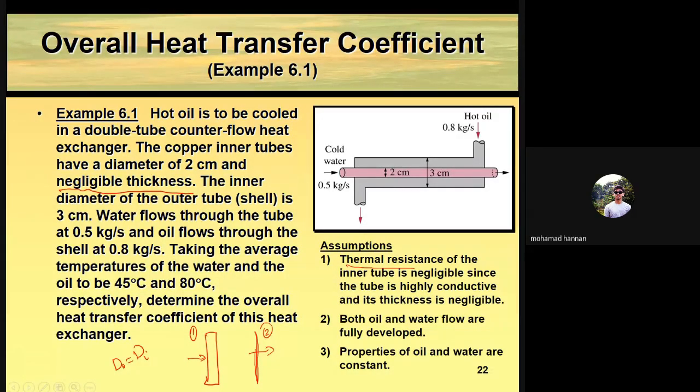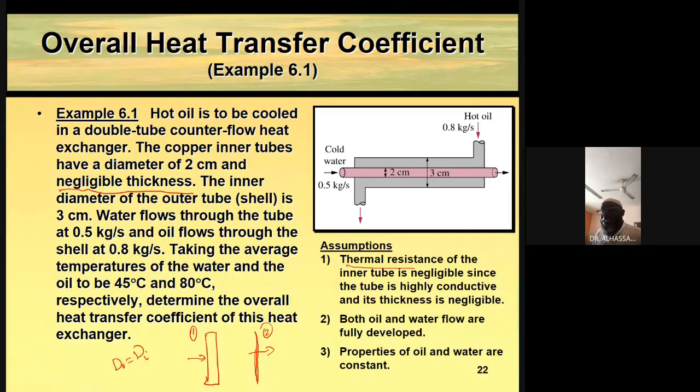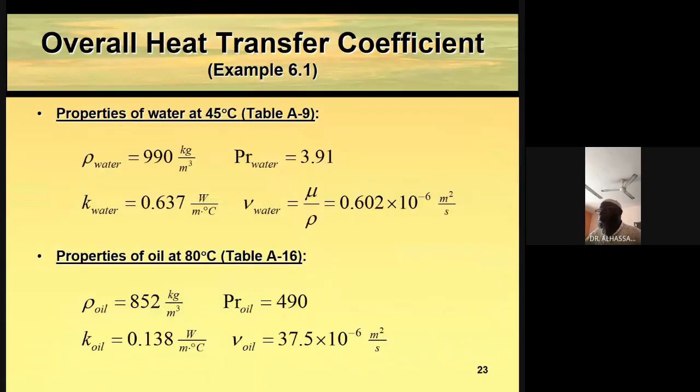So the car radiator is also a heat exchanger. Yeah, of course. It's a cross flow heat exchanger, because the car radiator has a series of, let's say, flat tubes like this. So I'll say flat tubes. My drawing is not so good. So they have flat tubes. All car radiators have what we call flat tubes.